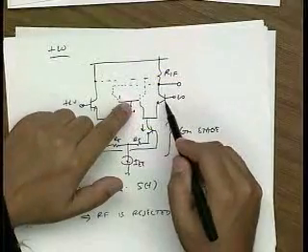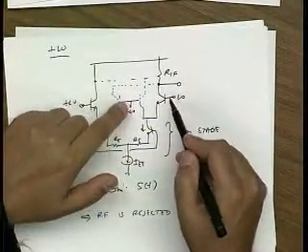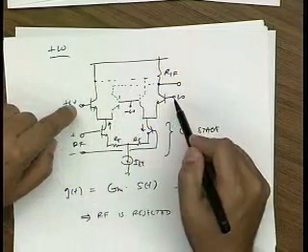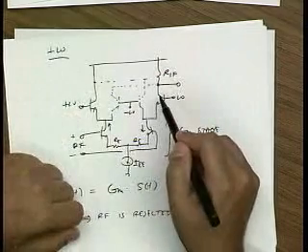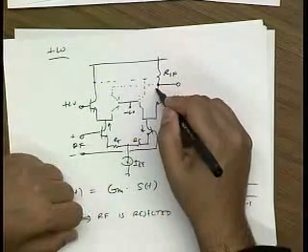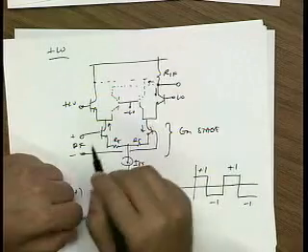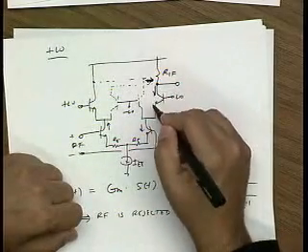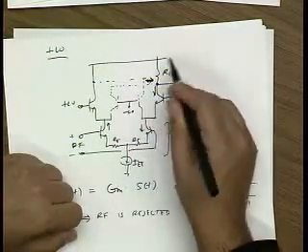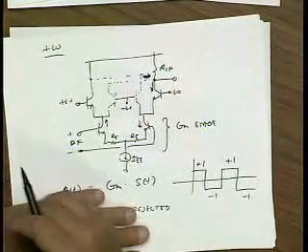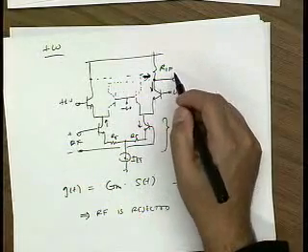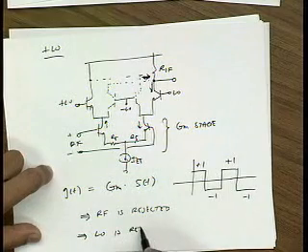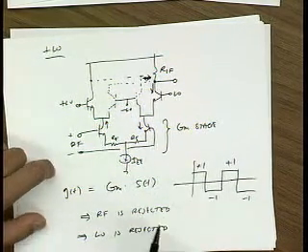So the gain from this path to the output is, let's say, GM1. The gain from this path to the output is minus GM1. So the LO perturbation, if these two paths are perfectly balanced, the current from here perfectly balances the current from here. So this current balances this current, and none of the LO current actually flows into the output. So this voltage will not move due to the LO voltage. So the LO is also rejected. Okay.